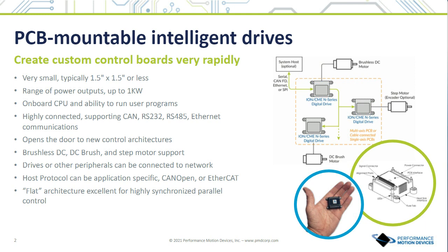So with this kind of a smart drive, you're able to target all different motor types, so you can standardize on your machine design. And we support all sorts of higher-end protocols that the user runs, like CANopen or EtherCAT, that you can port onto these drives. It lends itself to a flat architecture where you have all of them connected, or we've come out with a new hierarchical architecture where the host just talks to one drive and it